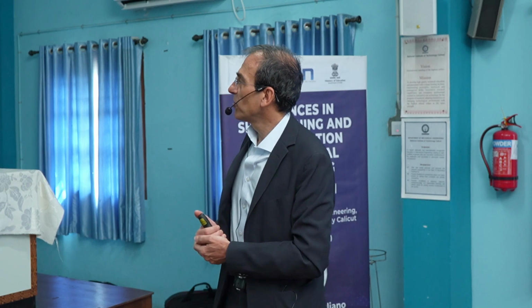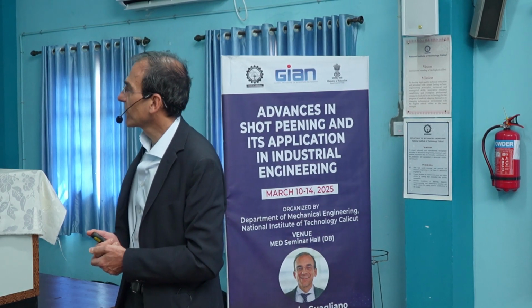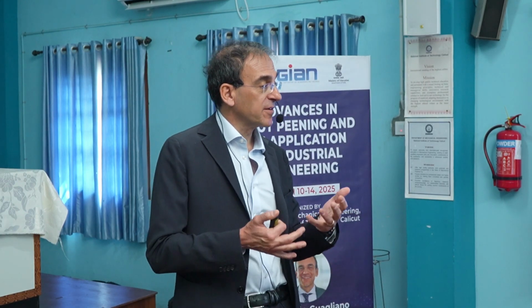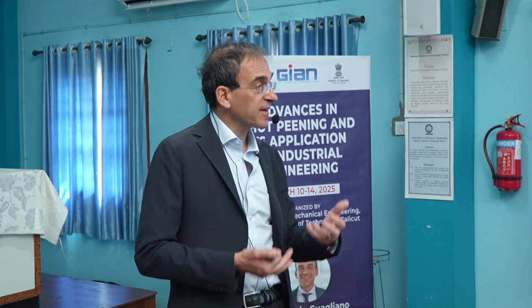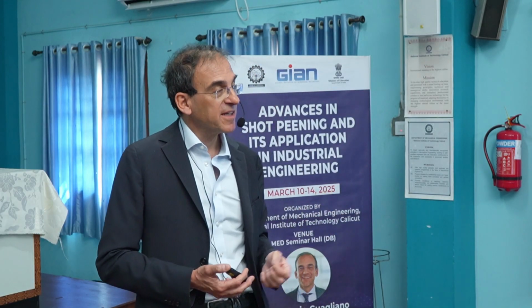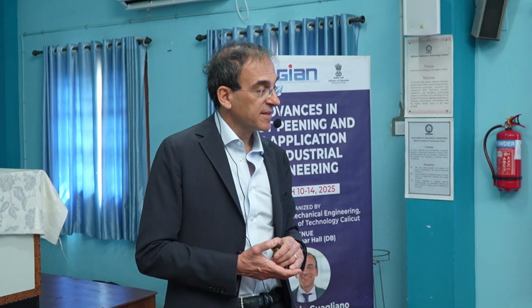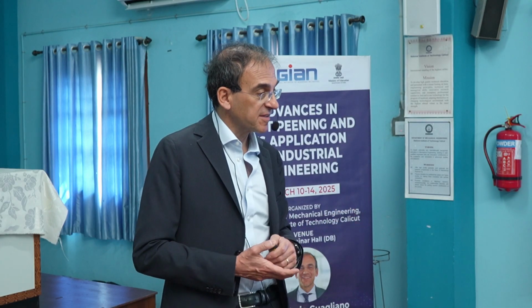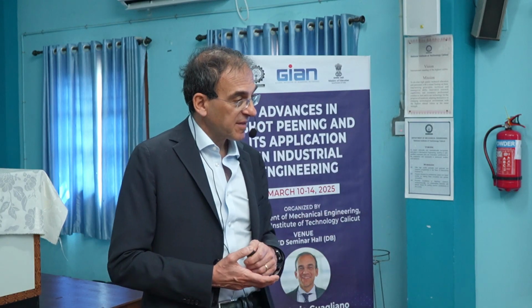And these are possible arrangements of the nozzle. So we can have a cylindrical convergent nozzle, a cylindrical nozzle, and a converging and diverging nozzle. Indeed, converging and diverging are not necessary. We are not at the speed of sound; we are much less than the speed of sound in this case. But anyway, they can be used. The cylindrical nozzles are generally used. The straight one is not used anyway.